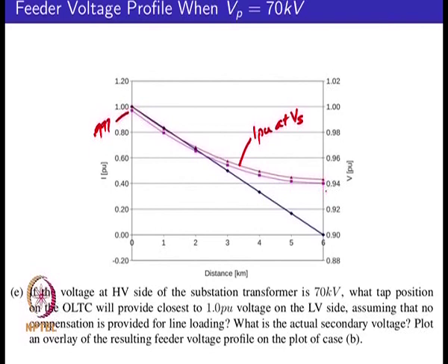So it is not necessary that you have a higher voltage on your primary, you will see the same effect on the secondary. Depending on the tap selection, you could have a voltage which could be on either side. Again, this is because of the finite quantization effects. You have only 9 taps, you do not have a smooth variation of the taps starting from say your minimum value to your maximum value.